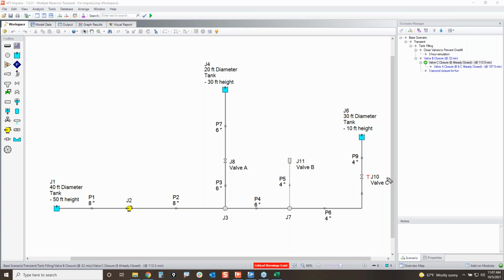And so now, here's what's going to happen. When this valve closes, you're going to see that high pressure surge propagate down through this path right here, and then it splits. It's going to split up in this direction, and it's going to continue down, and it's going to split back towards the pump and split up this direction. Well, this is a reflecting point.